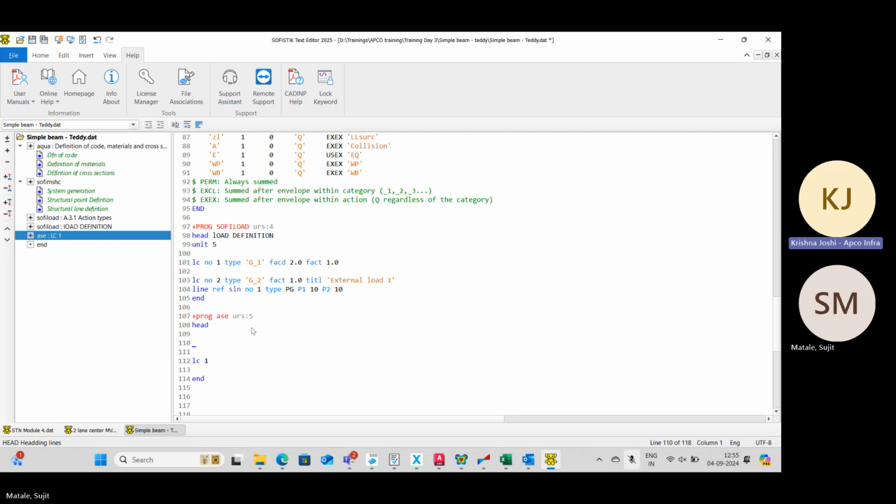This is the free vibration. If your time history is so shaky like this, too shaky with all of the frequencies. But if you filter out for one mode, in the direction in which you want the time period, you get such a nice curve like this, showing a very well damped structure. But you should be able to filter.